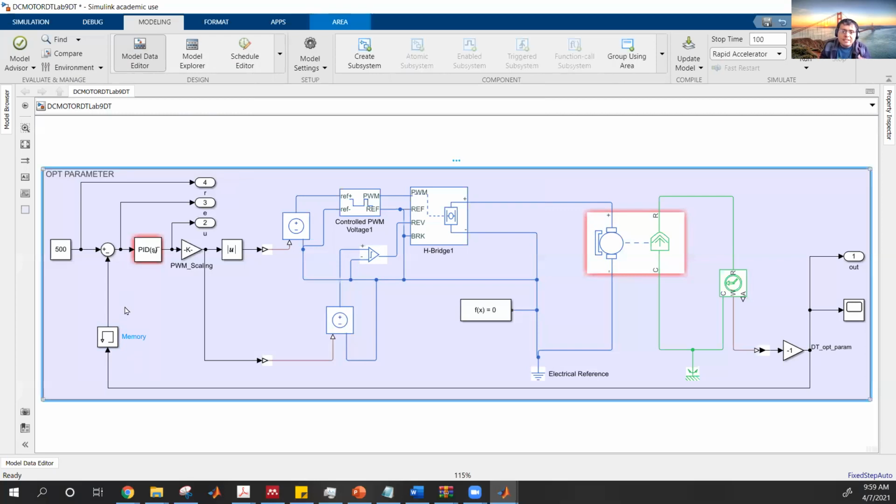According to the ODE solver that you use, the solvers sometimes assume initial conditions to satisfy something called algebraic loops. Simulink doesn't know which is the initial condition when it starts, and by default Simulink sets the initial condition to 0.